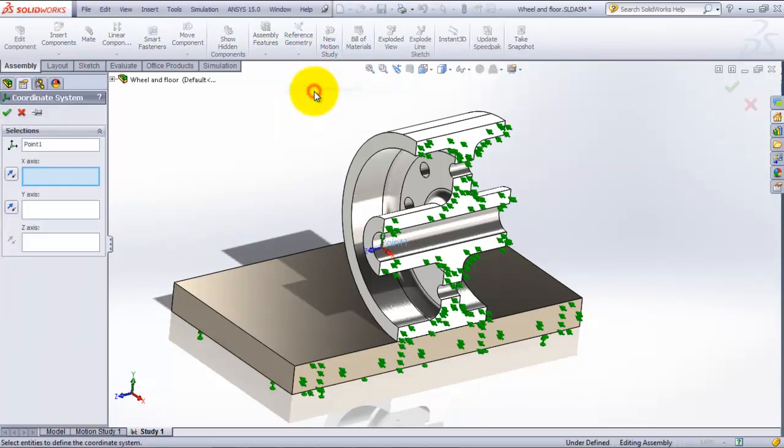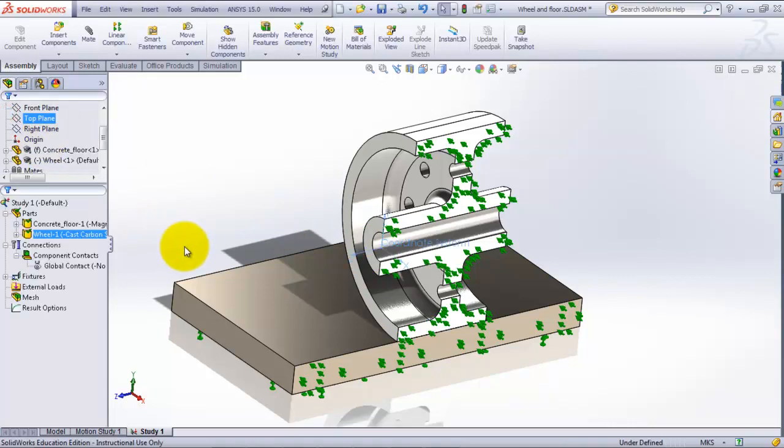So go to the coordinate system now. The x-axis, well, we got 0.1. That's the big thing we want. The x-axis, the z-axis, we're okay with what we have. We basically want the z-axis to be aligned with the axis of our hole. So if it's aligned already, we don't have to do anything else. We can just check it. It's okay where it's at. All right, so that coordinate system is already active.